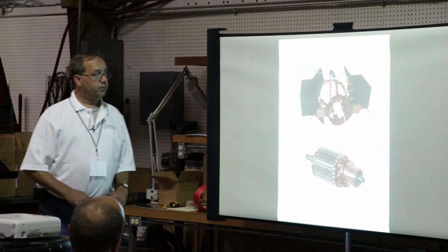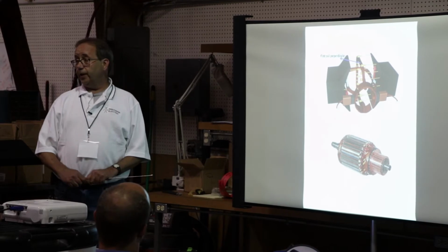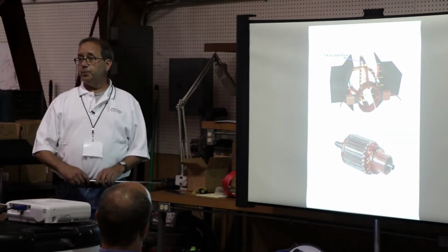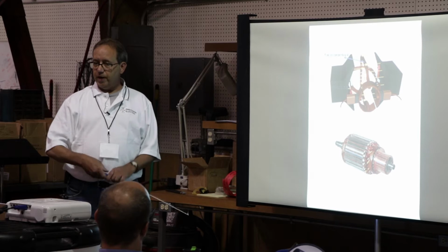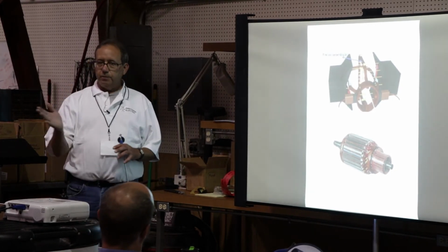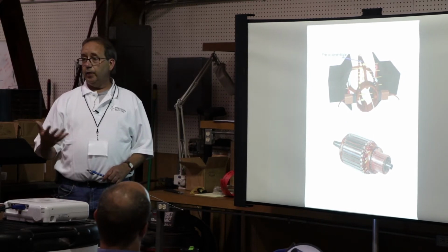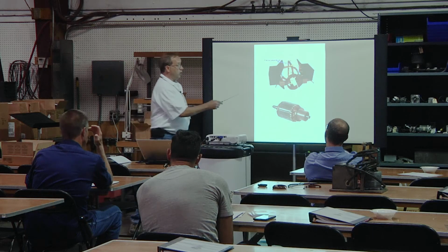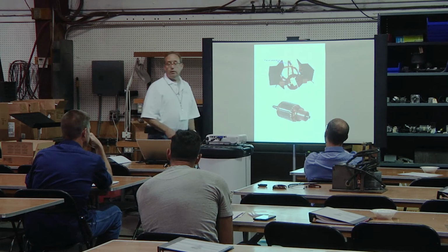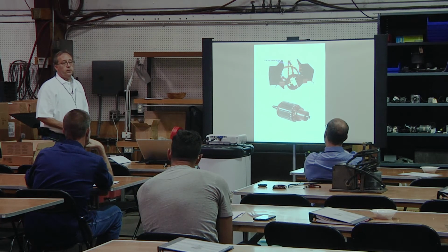So what's going to control the back EMF is generally two things. The speed. If you notice, the faster we move that magnet in and out of that coil, the higher the needle pegs, right? So the faster it rotates, the more back EMF we have, and the stronger that these fields are, the more back EMF we're going to have. So that's what's limiting your armature current.